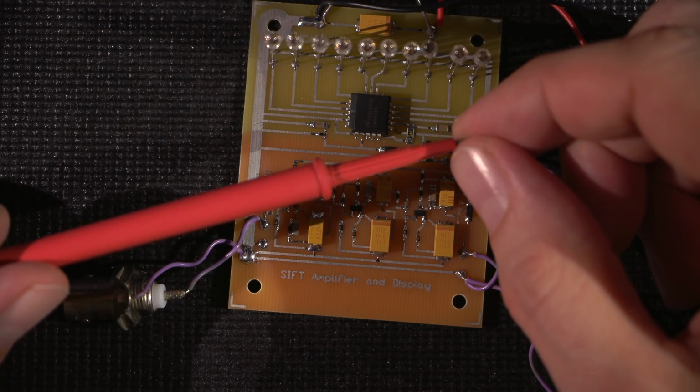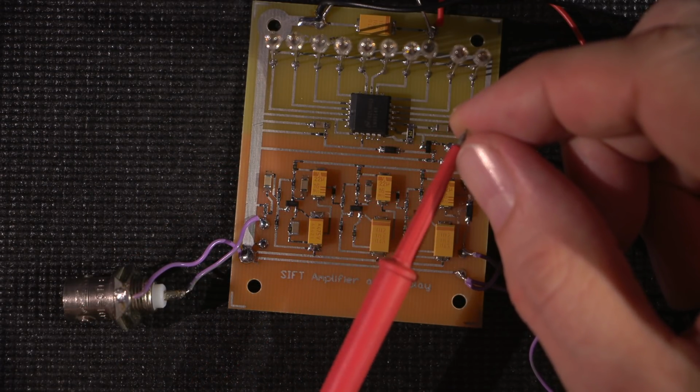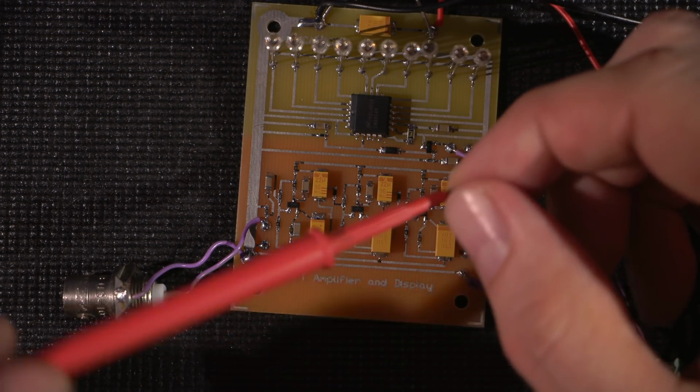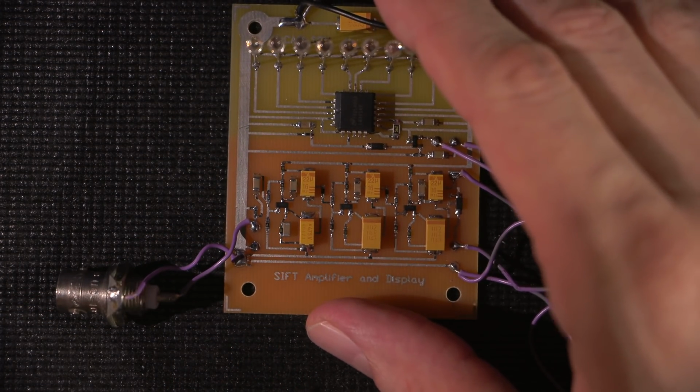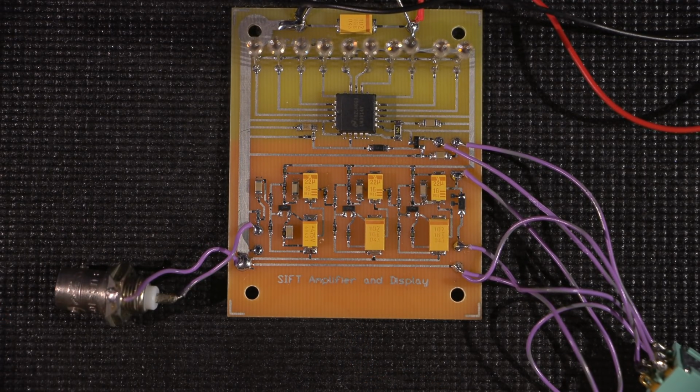So you would want this just before that point to where it goes click. That's basically what bias is: you're getting rid of all this area in the bottom, and that's what these resistors do. It's basically just getting ready to turn that transistor on.